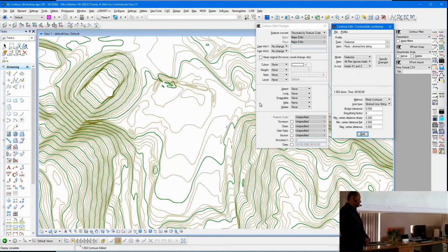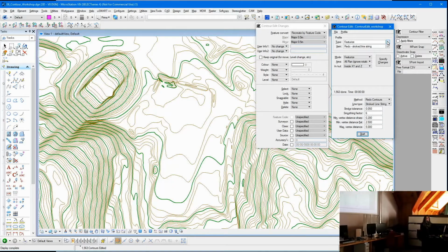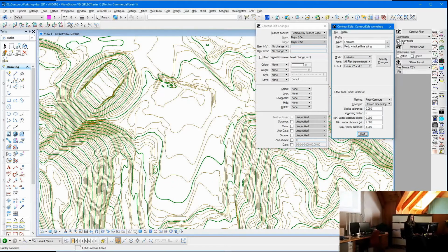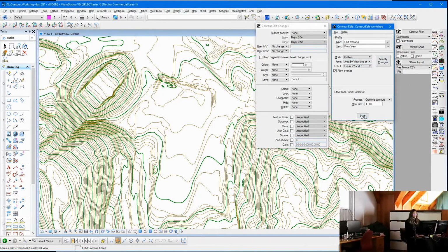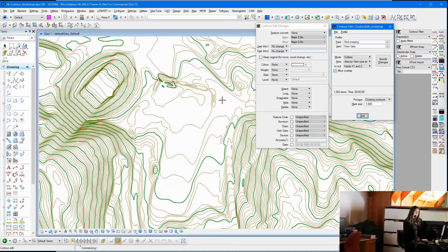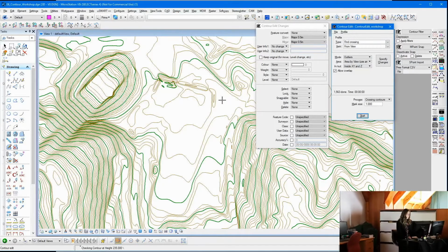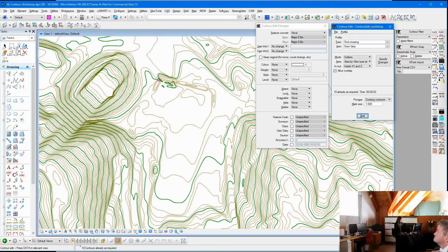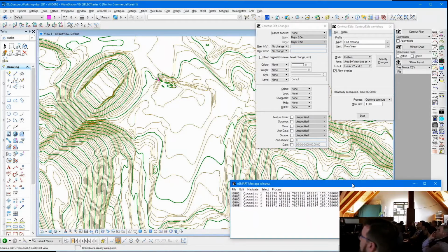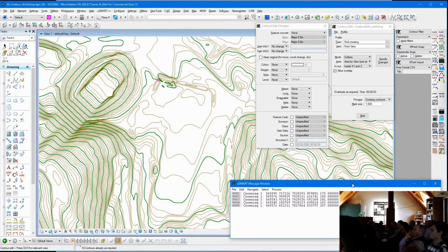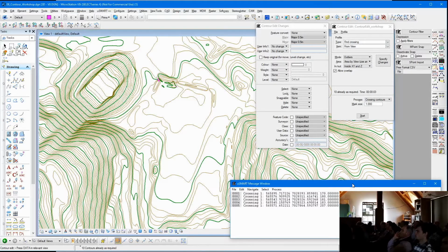We're just going to find some crossing contours. I know sometimes it's a problem. We'll hope that doesn't happen, but sometimes it does happen. In theory, if your DTM is rock solid, you won't get crossing contours. But it happens. Your DTM is just not dense enough to control the contours enough.